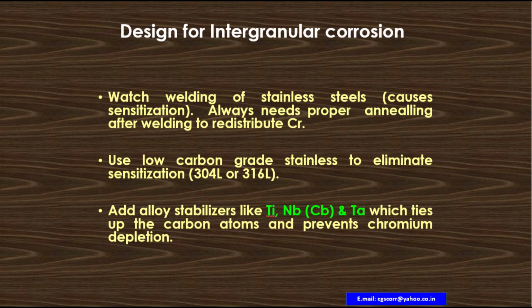Design for intergranular corrosion: how to minimize, how to prevent intergranular attack. Watch welding of stainless steels, which causes sensitization. Always use proper annealing after welding to redistribute chromium.